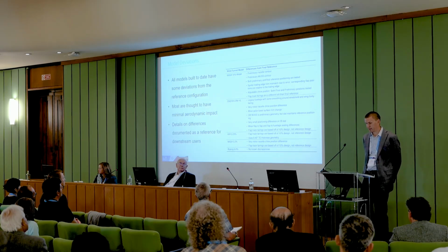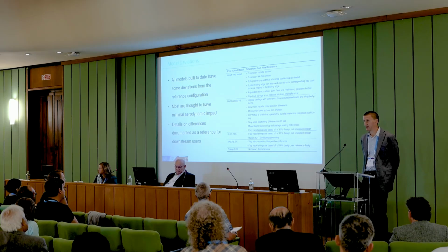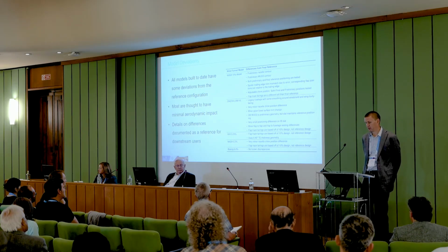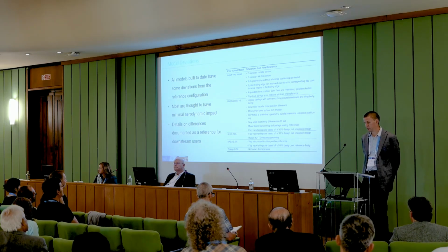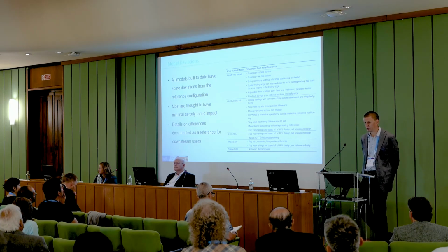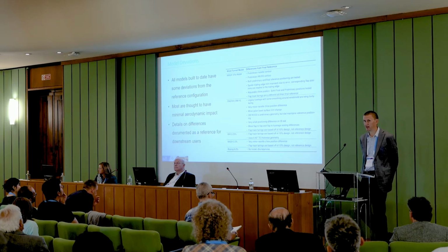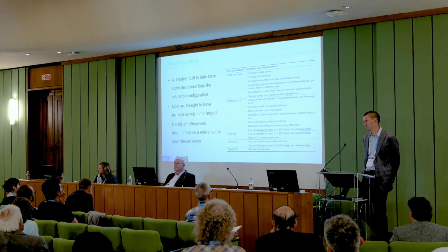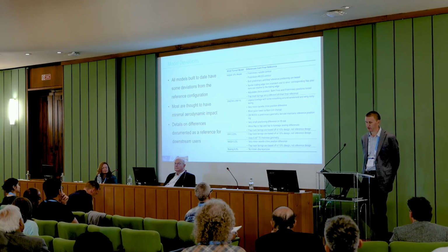So starting with the NASA 10% model, that was the one, again, that was defined based on the 2016 paper. So things changed based on that first test. This one has a couple of loft differences. The nacelle contour was made a little bit less aggressive. We saw some flow separation on the nacelle in that first test that we didn't want to be a feature of this model, so the nacelle was recontoured.